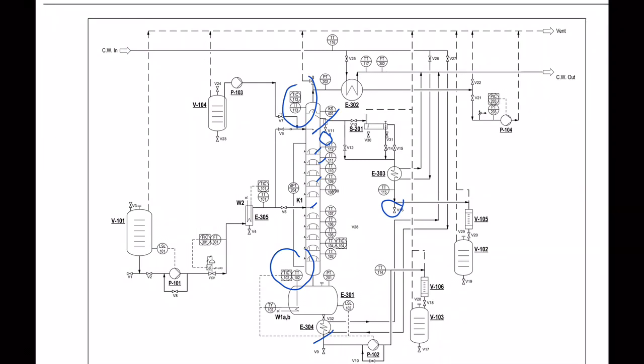After you set the reflux divider to position 1, then you can open the valve V11 to collect enough sample of the top product. Then after the sample is enough from the V11, you can close back the valve V11.